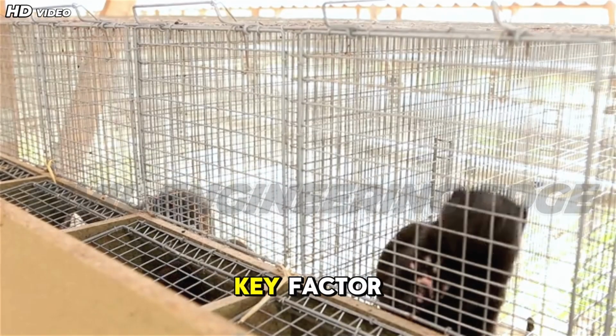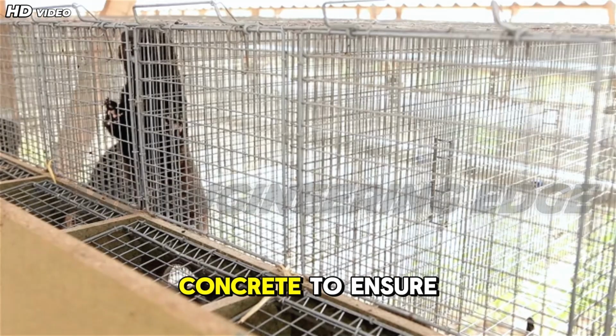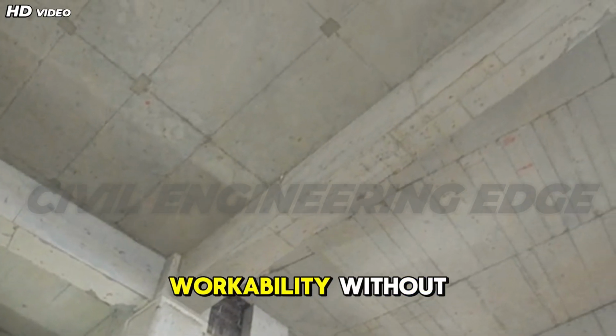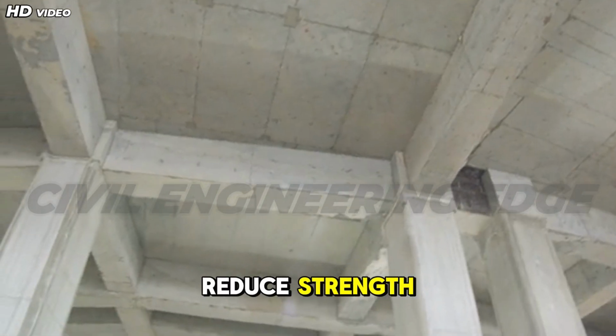Workability is another key factor. Columns with congested reinforcement require workable concrete to ensure proper compaction. Admixtures may be used to improve workability without increasing water content, which would otherwise reduce strength.